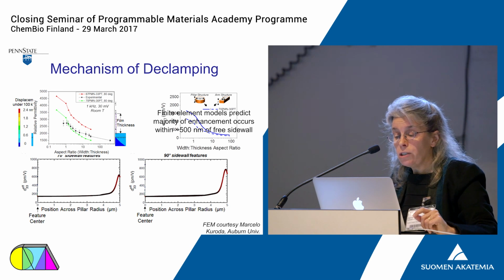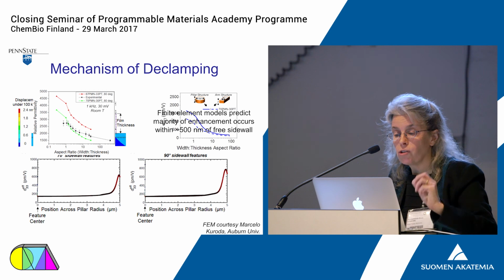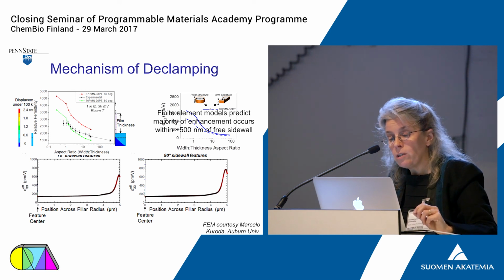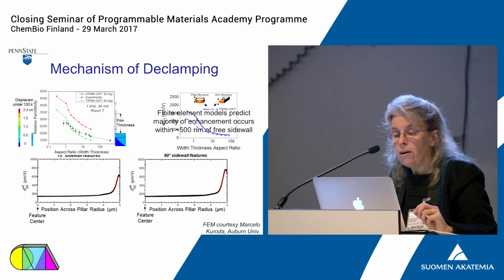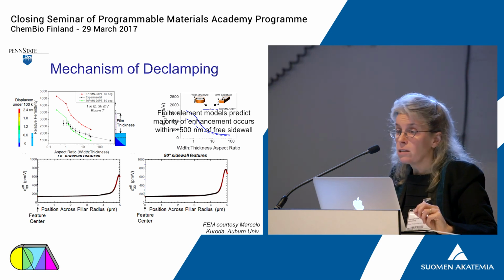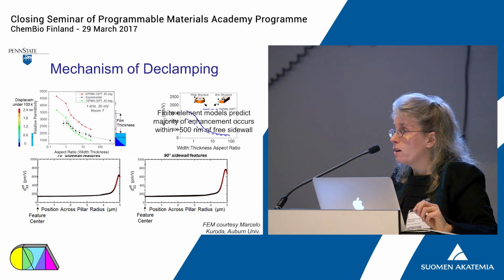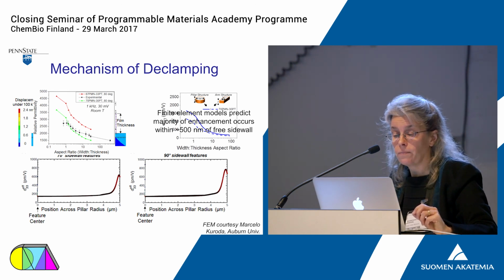To assess how we should be able to change the piezoelectric coefficient, we used finite element modeling. We looked both at a 70-degree sidewall angle and a 90-degree sidewall angle for pillar and strip structures. And what you see is that when you can drop to a width to thickness aspect ratio on the order of 1, you can get to properties that are good enough for this device actually to give you what you need to replace the silicon transistor.